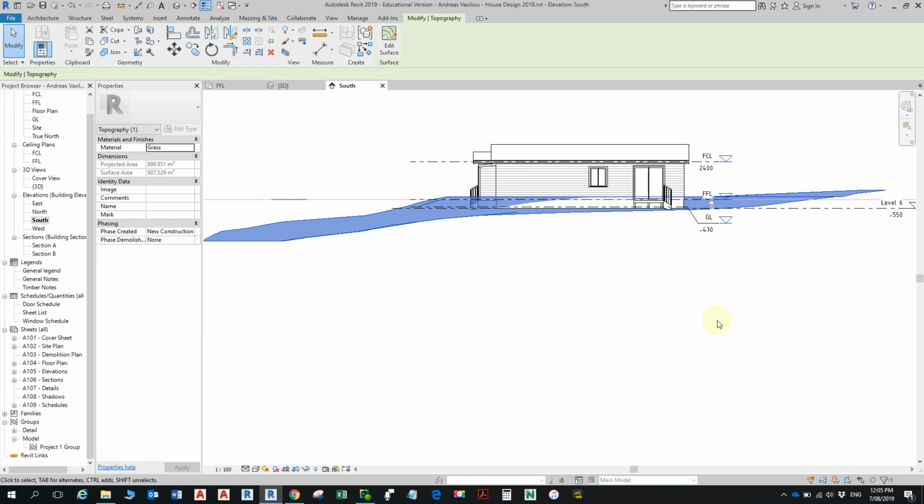Right. That doesn't mean that you never need to have a retaining wall under a meter. Sometimes you do, with that council say yes you do. But if we keep things under a meter, so much simpler. All right. So we try and keep the cutting and filling, I suppose, under a meter, so there's not too much engineering required, if any.